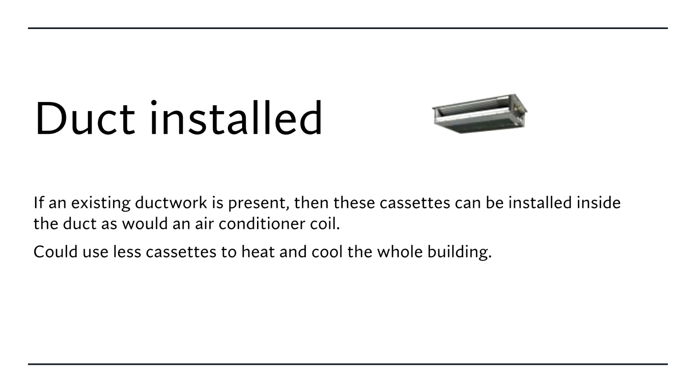So in order to get this into operation, we are probably going to have to modify the duct and make some improvements to the air distribution of the house. Again, that's going to raise your cost. In the long run, you'll have a much better operating system by doing this. And you can have less of these involved because your duct system is usually zoned to get air into all the right places inside your whole building.